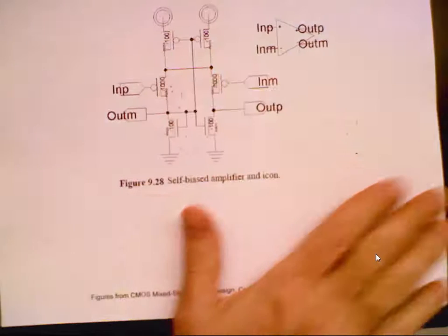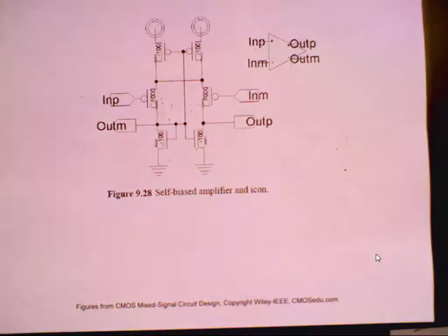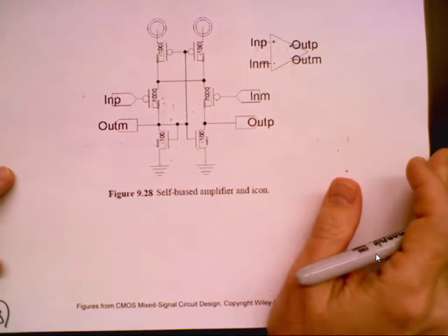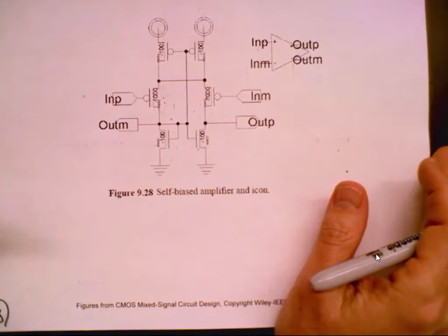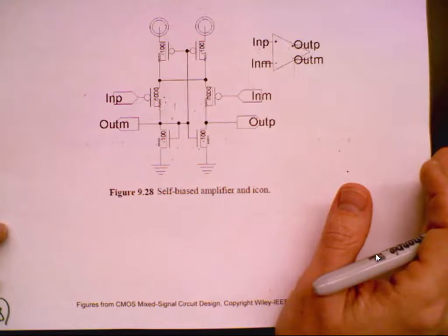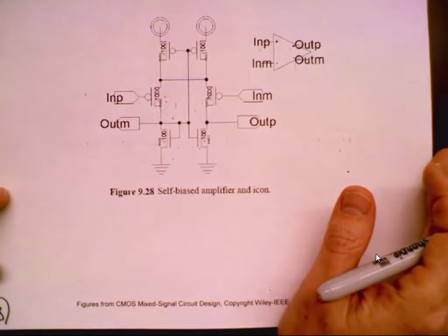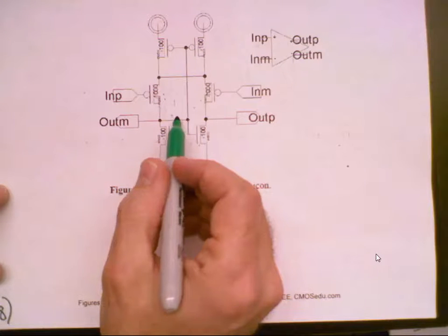This circuit, one of the big things here is you don't have slew rate limitations, and so that's one of the big benefits of using this topology. But what's the big drawback? Yeah, the gain is low, right? It's high speed, doesn't have slew rate, but the gain is not good. And the out minus isn't going to swing much at all, right?